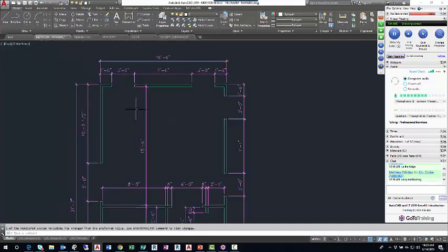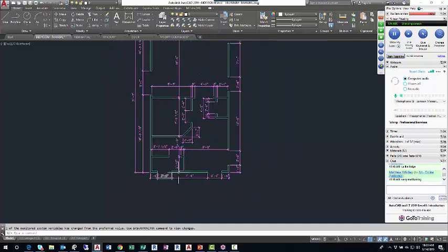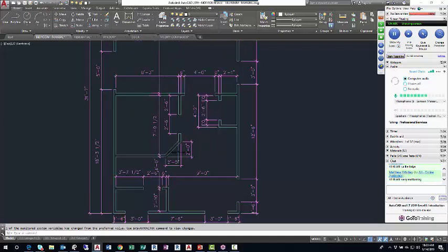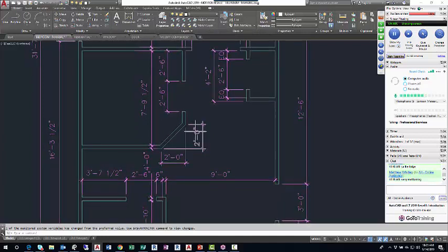So we'll use the chamfer command in this basic floor plan. There are 2 closets, 3 if you want to count the water closet. The large closet has a chamfered corner that would, in interior design terms, facilitate easy flow of traffic. We just use it to say, hey, here's how you chamfer. So the chamfer distances here are 2 feet in the vertical, 2 feet in the horizontal. The chamfer command wouldn't say vertical or horizontal. It would say chamfer dist 1 or distance 1, chamfer dist 2.